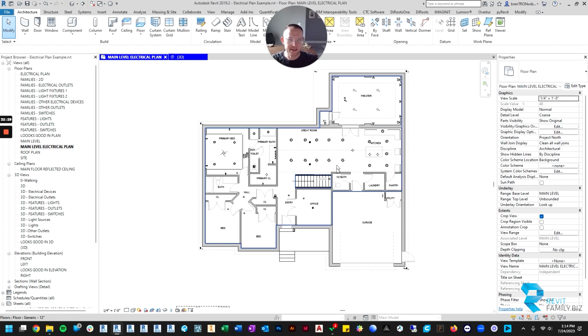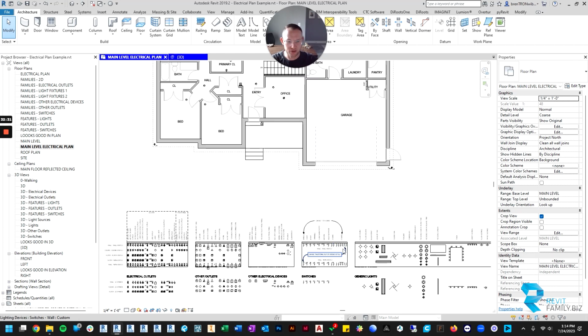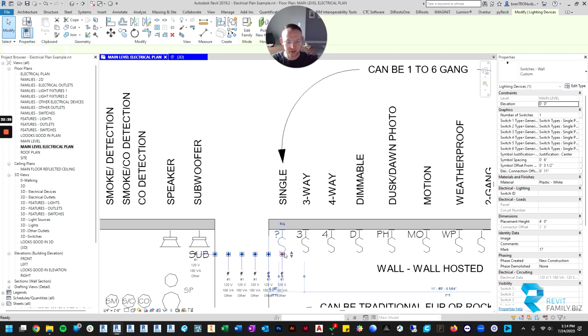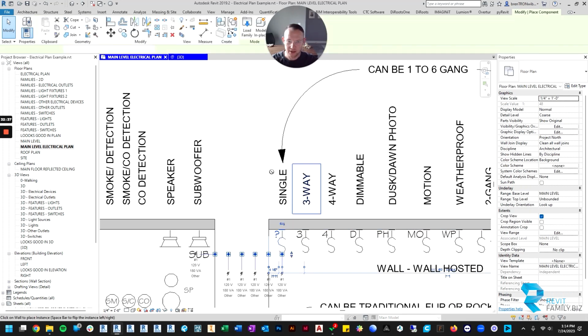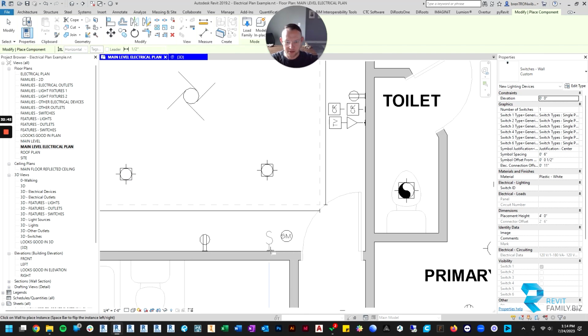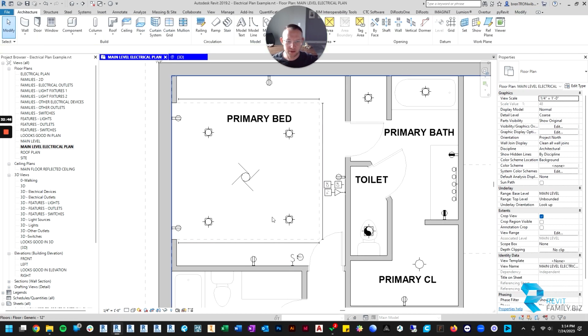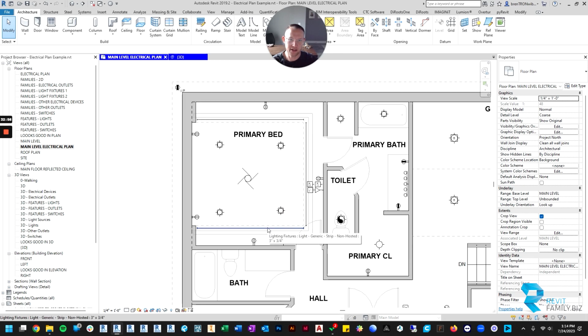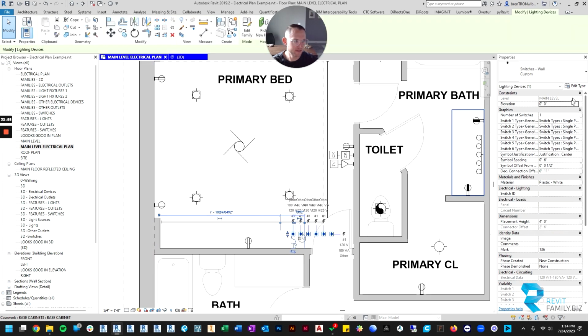Now we've got our lights in, we can go through and do our switches. So I like to start with just the single switch. And let's just go through this really quickly. So the switch will most likely be right here by the door. And now I just think about the locations and what I want switched. So let's first talk about how many switches I need. I need the fan, I need the can lights, and I need the tray lights. So we need at least 3 switches.